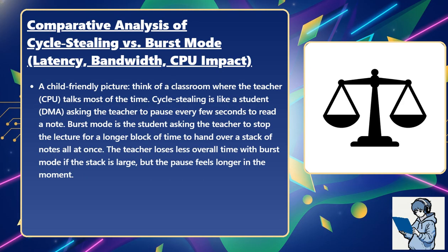A child-friendly picture. Think of a classroom where the teacher, the CPU, talks most of the time. Cycle stealing is like a student, DMA, asking the teacher to pause every few seconds to read a note. Burst mode is the student asking the teacher to stop the lecture for a longer block of time to hand over a stack of notes all at once. The teacher loses less overall time with burst mode if the stack is large, but the pause feels longer in the moment.